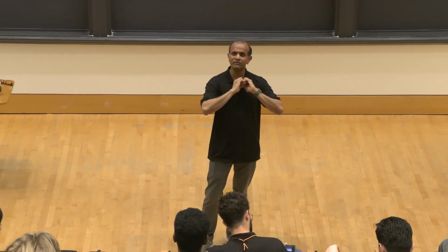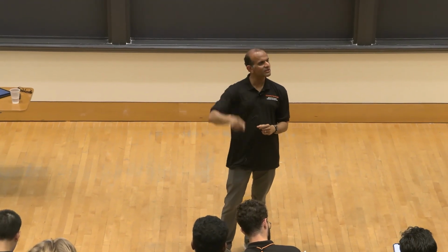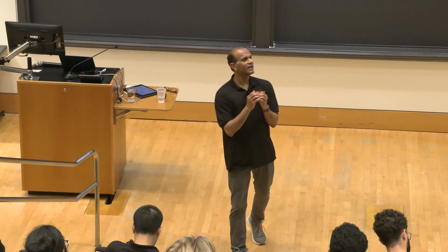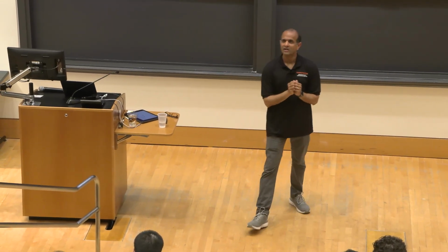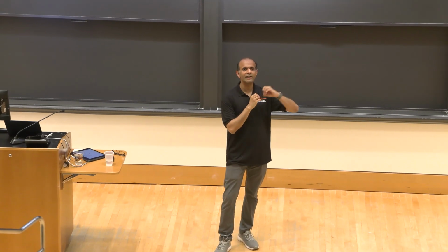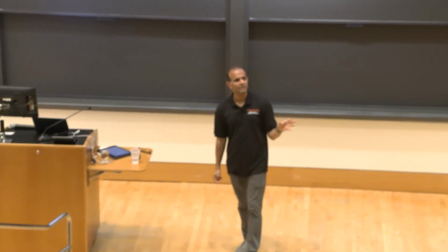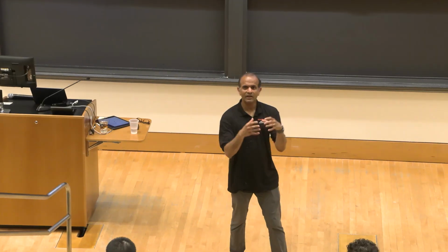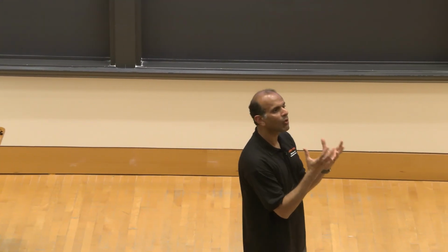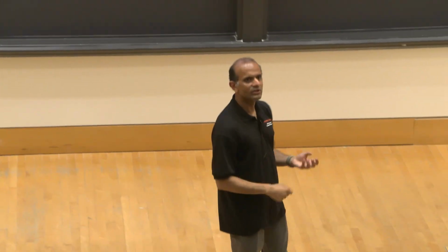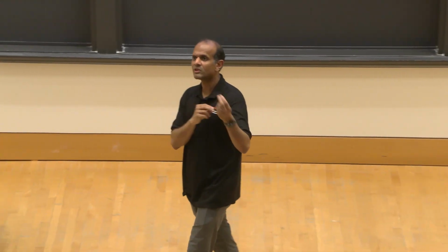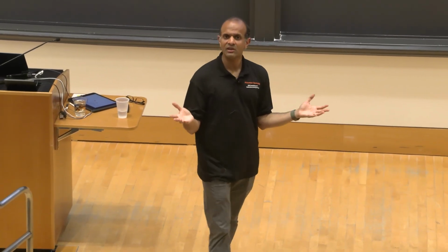So if a flow is very turbulent and you make any change to the flow, it will immediately get rid of that change. But if you have a very low velocity flow and you make any change to the flow, intuitively we can think about it, right? It will take a very long time for the change to go away. So now we have a system where there are low velocity and high velocity regions, and you need a quantity that depends on that memory. Temperature is not that quantity. You need something like soot or NOx. And now you have a very different flow system.